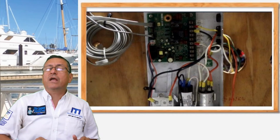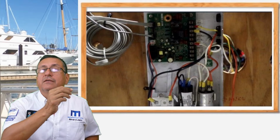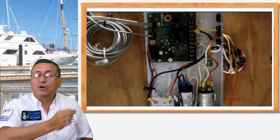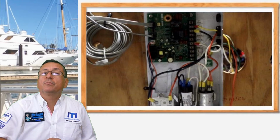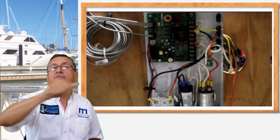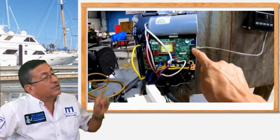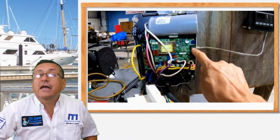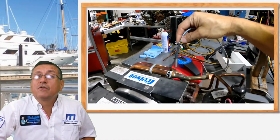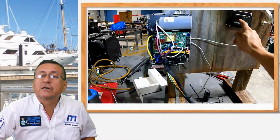Okay, in other words, we are going to check in the control box where is located the output for power for the blower, power for the raw water pump, and we are going to verify where is located the terminal for the power coming in from the main breaker of the AC panel. And we are going to check where is the connection of the data cable from the thermostat. And where is the connection of the data cable from the sensor located in front of the air filter.